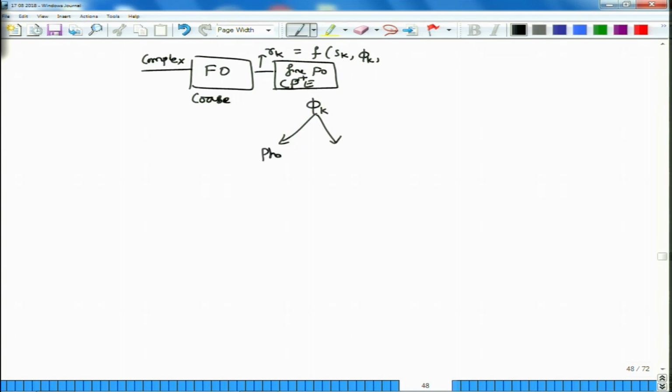One is a phase offset. This phase offset means that, let us say, the carrier phase is 45 degrees and constant. It may not be, I am just writing it in that way. Then the phase of the local oscillator may be, say, 30 degrees. So in this case the phase offset, or what is sometimes called the nominal phase offset, is about 15 degrees. But the phase is not going to be constant in this manner. It is actually going to be varying around this 45 degrees, and similarly the phase noise of the local oscillator will also be varying, or the phase of the oscillator will also be varying.